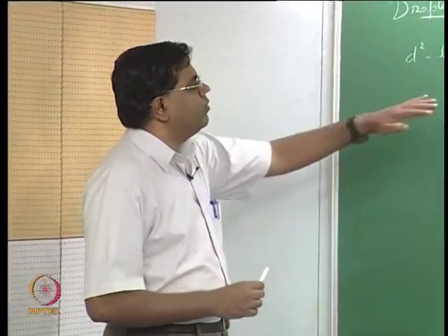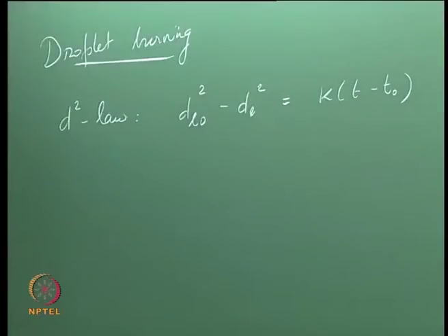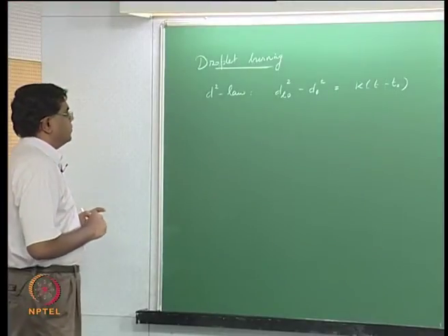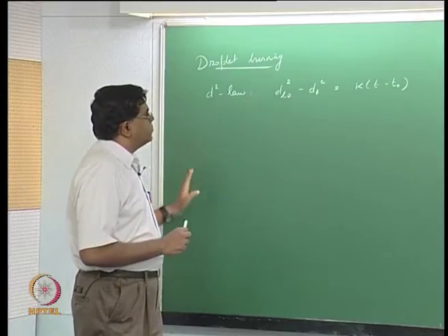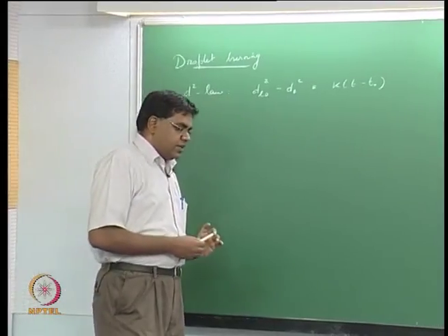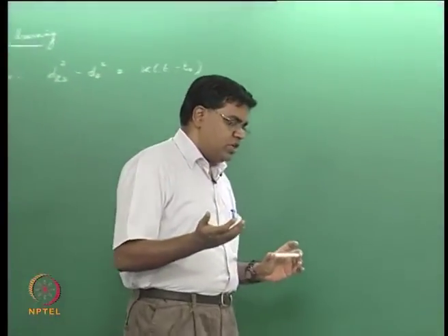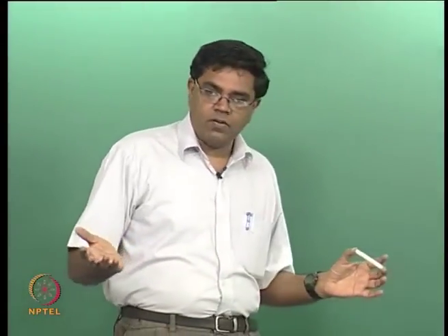So whatever we are talking about now will also be valid for evaporation in a hotter ambience than the liquid droplet temperature. And when we say d squared, it basically refers to surface area. As a matter of fact, the goal of atomization is to enormously increase the surface area of the liquid from originally, let's say, a flow of bulk liquid.